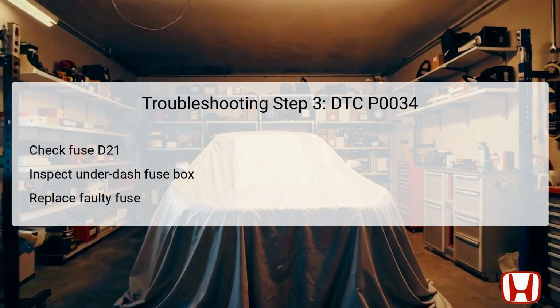This step is crucial, as a blown fuse can prevent proper signaling to the turbocharger solenoid, resulting in low voltage conditions. In this step, turn the vehicle's ignition to the on mode while ensuring the solenoid valve 2P connector remains disconnected. Utilize a multimeter to measure the voltage between the designated test points, the female terminal number 2 of the solenoid connector, and a suitable body ground. This measurement aims to confirm if there is battery voltage present at the solenoid's input.